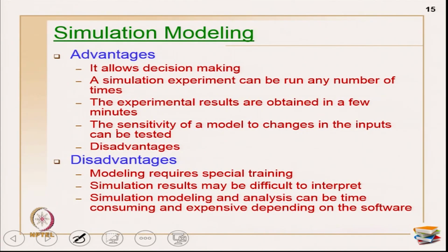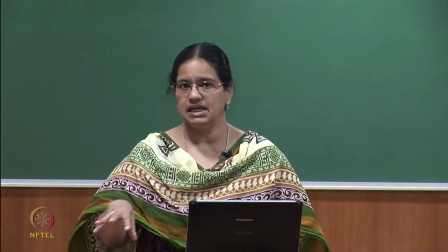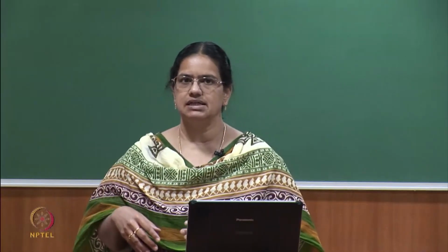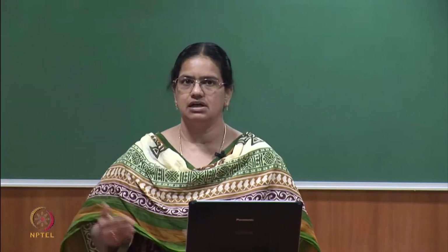Okay. Now, what are the advantages of simulation? Because I introduced you to simulation, you should know a little more on what is simulation. Advantages, it allows decision making. The primary advantage of going ahead with a simulation model, as an experimental technique, is that it allows decision making, because you cannot really make trucks move on the road and then calculate and do something. You have to really take decisions on how many trucks I need, how many loaders I need, how many excavators I need. Those decisions cover how much time the equipment is waiting in the spots, how much time the resources are taking, and then whether I can cut down the duration here and so on.